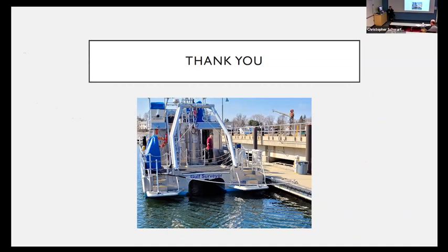A TCB system is installed on the same non-hydrographic boats, except instead of just simply logging the depth message from whatever echosounder is installed, we do that, but we couple that with a positioning system and a low latency data logging method to try to reduce the uncertainties and allow us to quantify the uncertainties associated with those soundings. So that's where the trusted part comes in. That's the trusted idea.